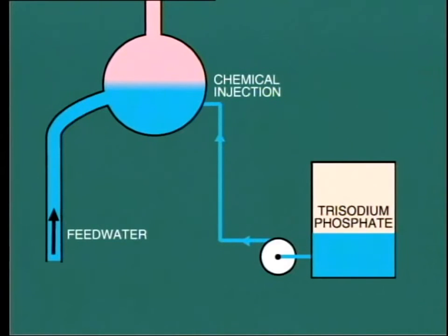For this reason, we find that the established control limits for boiler water pH are often reduced to a narrower range, say 8.5 to 9.5. In order to keep within this range, it may be necessary to use disodium phosphate instead of trisodium phosphate. The objective is to feed less sodium into the boiler with resultant reduction in free caustic.